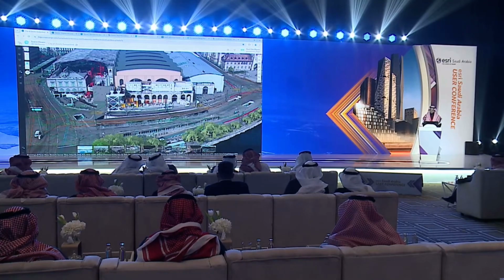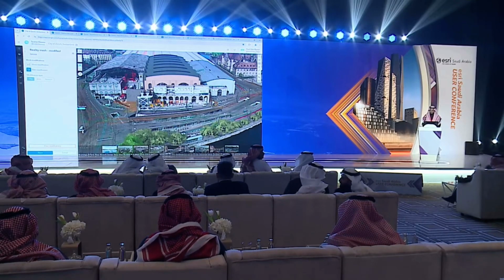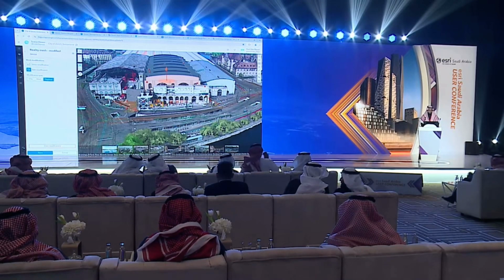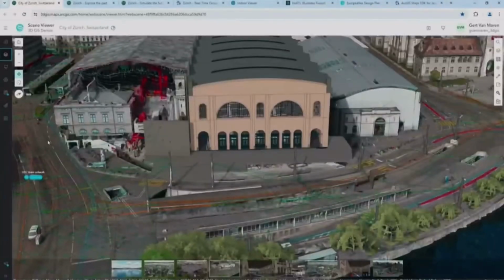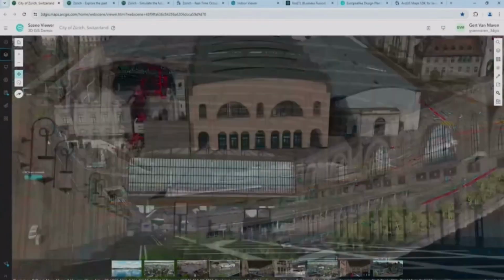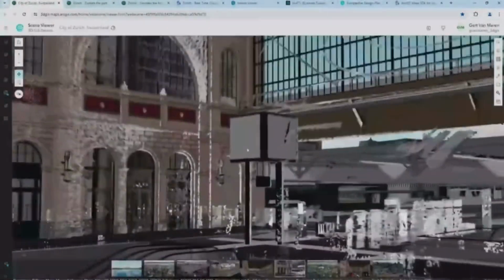This allows us to adjust the mesh directly in the scene viewer, ensuring that the BIM elements are visible alongside the 3D models. In the context of construction and design verification, we can add point clouds to help us verify the accuracy of the as-built conditions against the design.